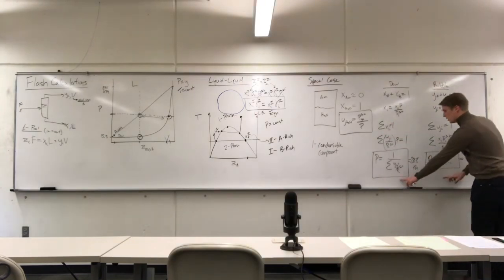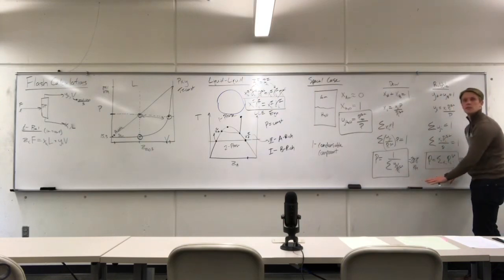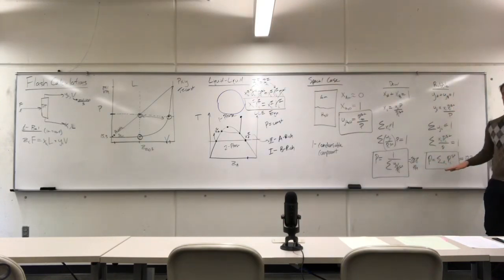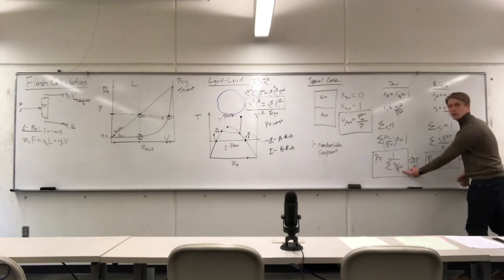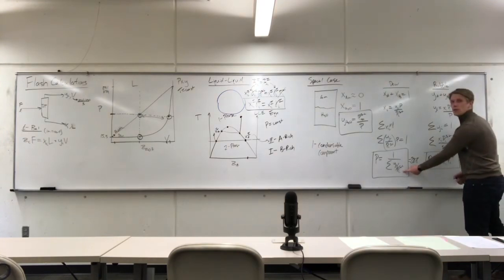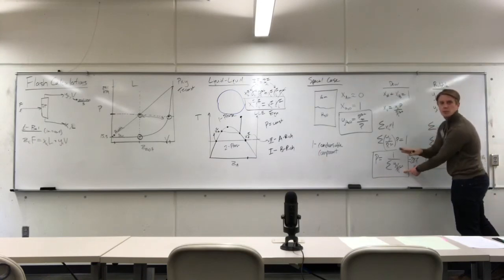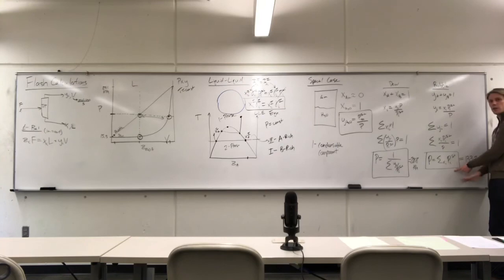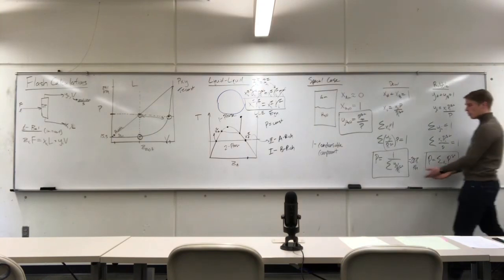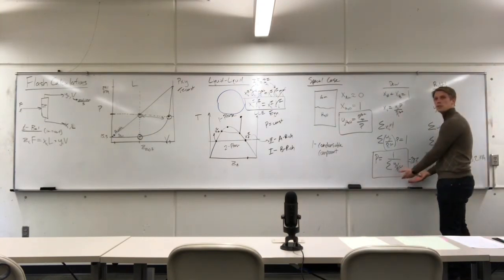One other takeaway here is that these equations that we derived, they're universal. They're 100% universal. So if I just gave you this equation here, you didn't do anything. All that you did was substitute 100% assumption-free equations into one another. This one here is 100% generalizable. I don't have to only apply this equation at the bubble point. I don't have to only apply this equation at the dew point.